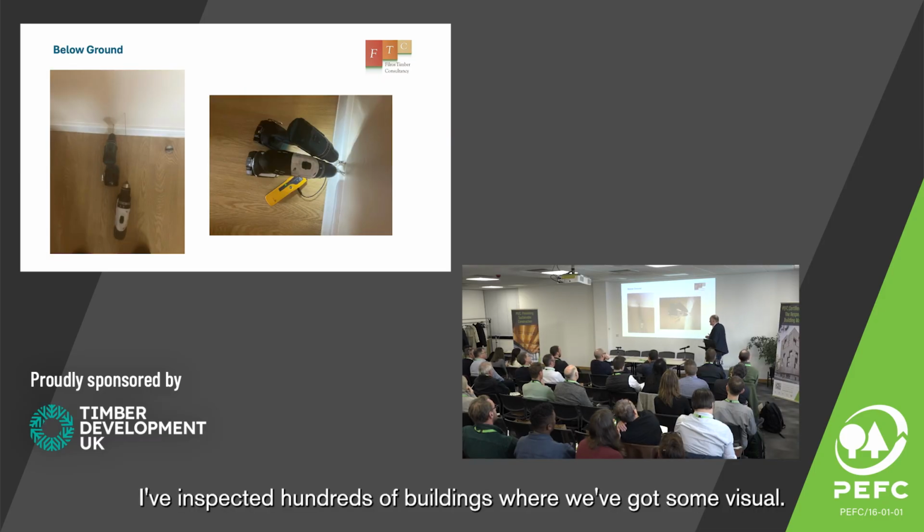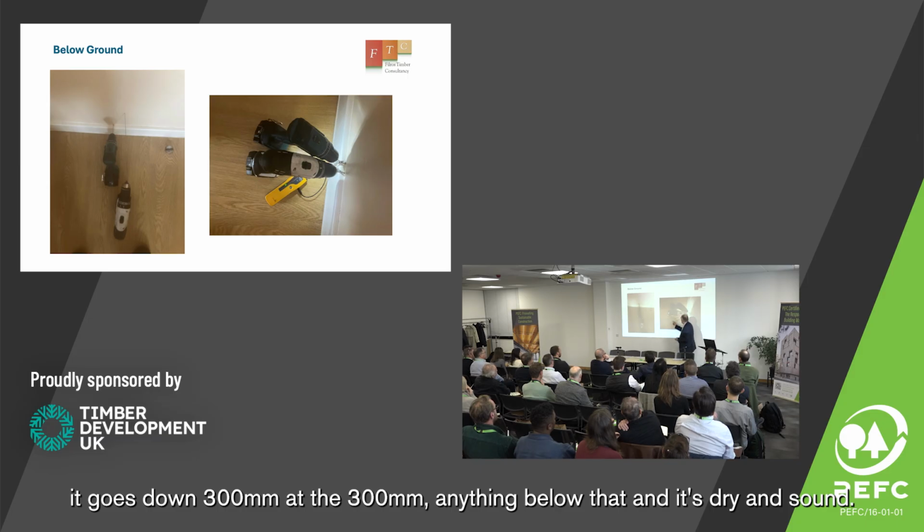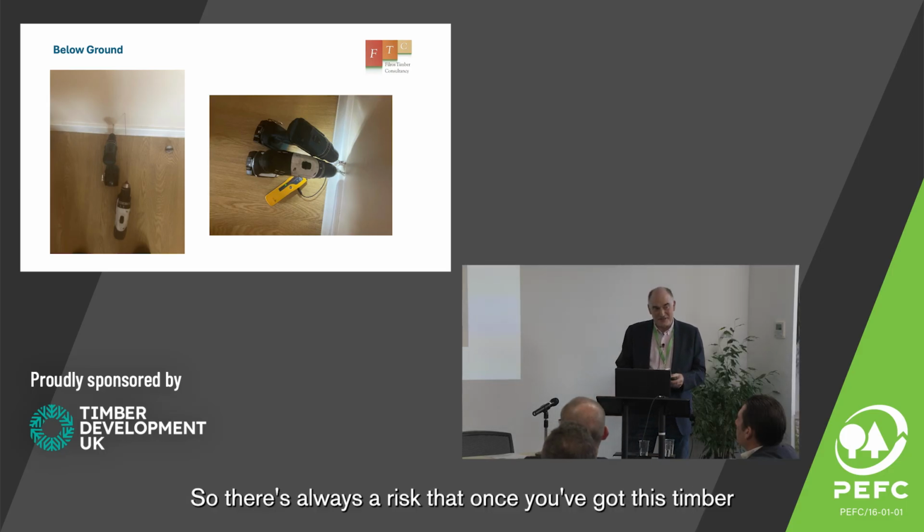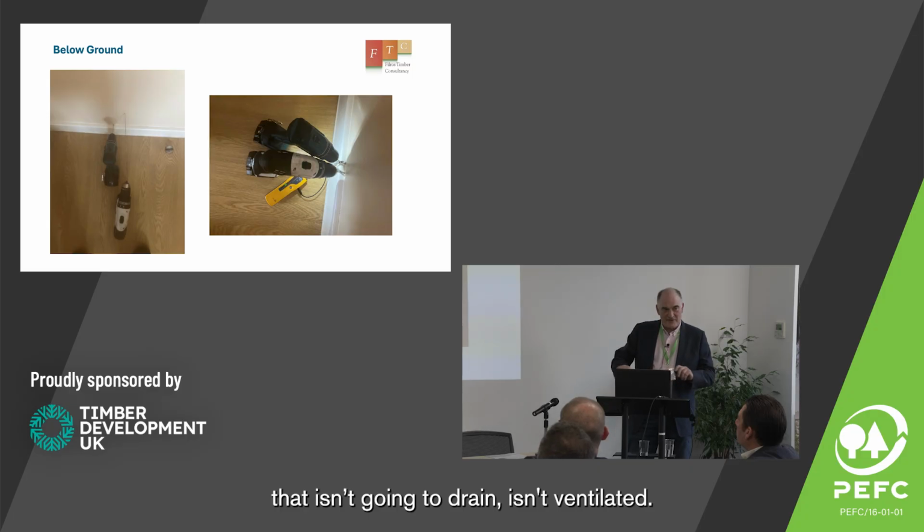I've inspected hundreds of buildings where we drill a fine drill bit down 300mm, and 150mm below that it's dry and sound. So it does work, but it only works when it works. There's always a risk that once you've got this timber that isn't going to drain and isn't going to be ventilated, what do we do when it gets wet?